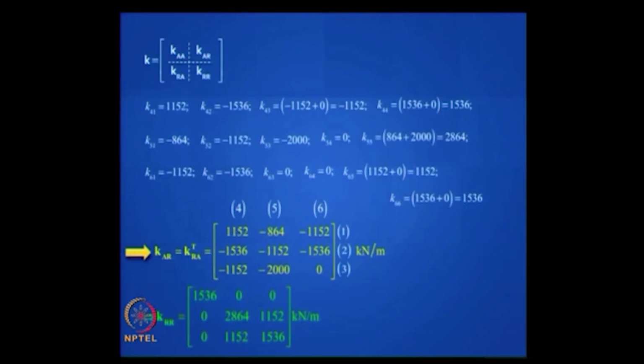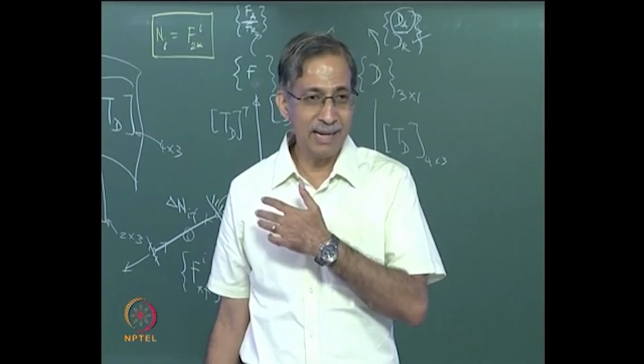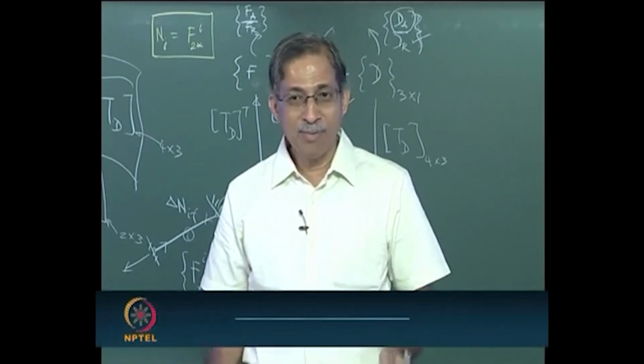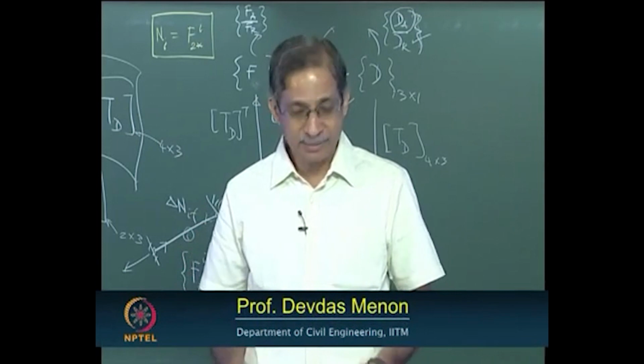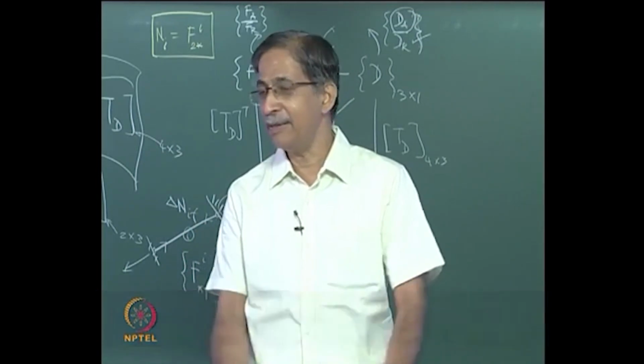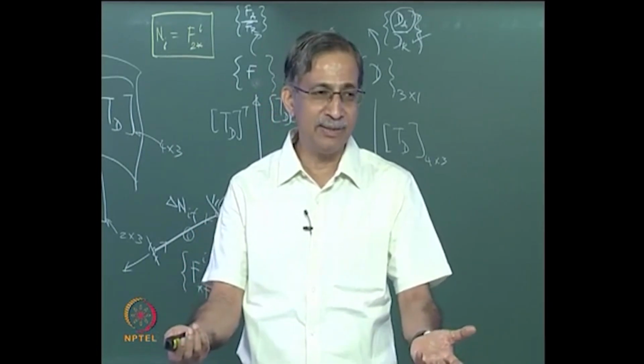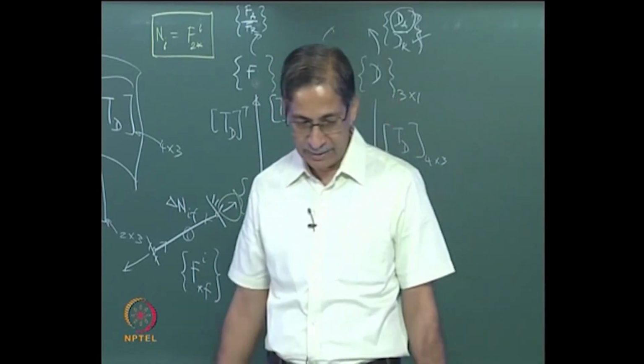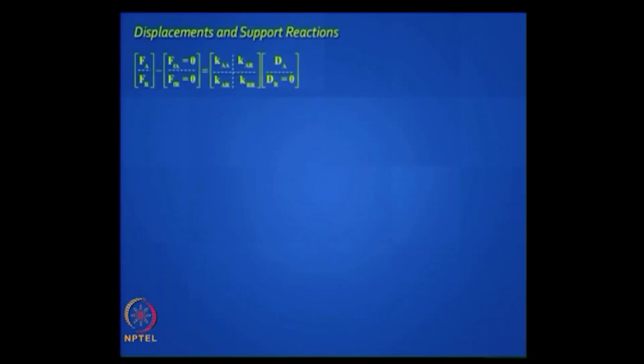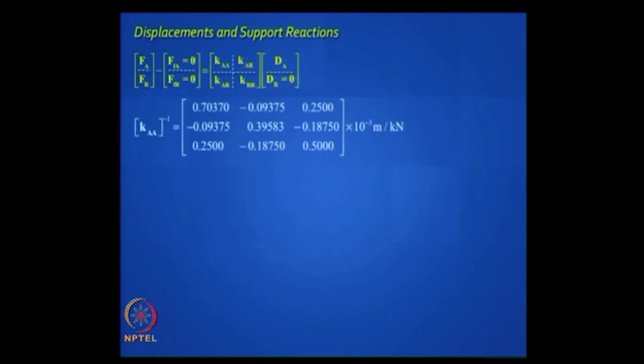Now forget this loading, you are ready to handle any loading on this structure including support settlements and temperature rise or lack of it. The moment you input the geometry of the truss, the computer will generate this matrix and say give me the load and I will give you the results, it is waiting. Okay. So how do you do that? In this particular problem you have no fixed end forces, right, dr is 0, there is no support settlement, so it is a straightforward calculation.